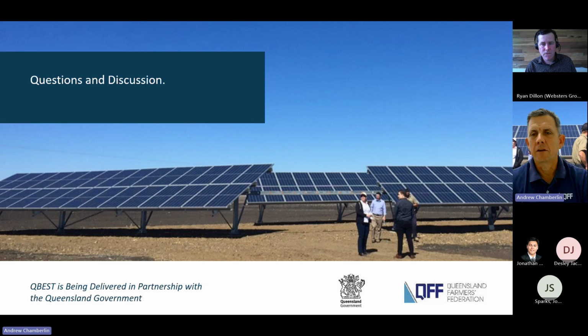Right, and also airflow for those condenser units, and good shading and airflow. Of course, sorry. The case study from the last webinar, I'd mentioned a couple of degrees temperature differential. We had something that was really packed tight into a shed for a milk vat, and there was a 10-degree temperature differential. So from the case study today, even 2 degrees with fans installed like it was designed, but it probably wasn't tested until you put the thermal camera on it and see, or a temperature data logger,